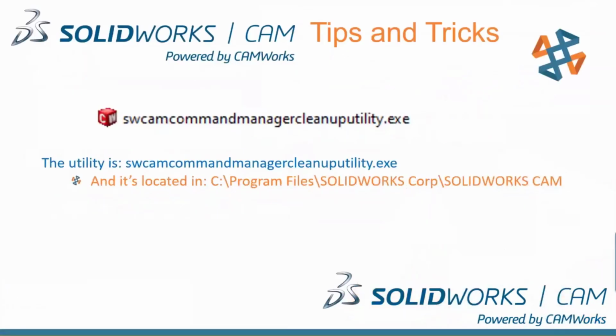My first one is where sometimes you toggle between turning your SolidWorks CAM on and off, and remember, SolidWorks CAM is an add-in. When I go up to my SolidWorks CAM add-ins and turn it on and off, or if you are a CamWorks user as well and toggle one off to use the other, sometimes they share the same menu, so you need to have SolidWorks CAM on and CamWorks off, and vice versa.